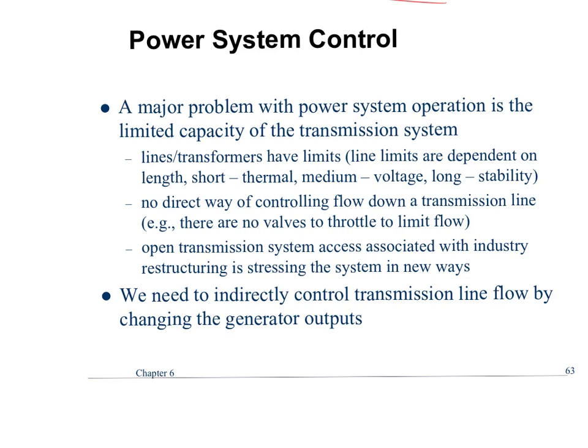Is that on like high load days? Yeah, typically it would be a high load day, or perhaps if something, like I said, when we talked about that contingency analysis, if a trip occurred and somebody hadn't postulated something correctly, maybe they had a voltage or a frequency that was lower than they expected when they did the study, and so it might have tripped offline. But at that point, you've got some explaining to do. If your UFLS trips because of an expected contingency, NERC is going to slap you around pretty good.